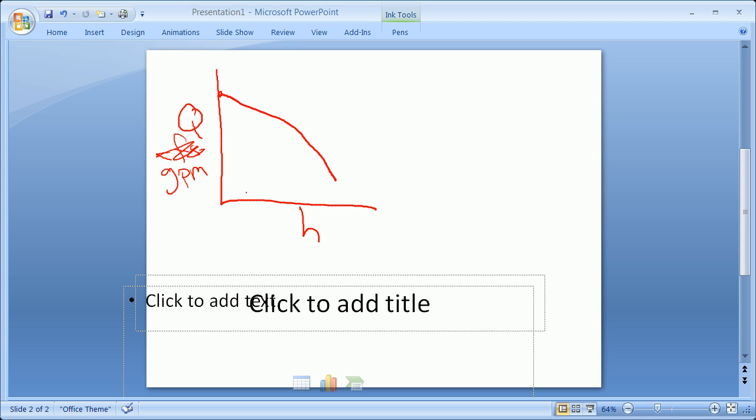If you start with the head being low, in other words just the static head, they start pumping a bunch of water, but because they're pumping a bunch of water, there's more head loss, therefore they pump less water, and they find this point where they operate, an operating point. A fair bit of engineering goes into the nuance of that. There is one other curve shown on a pump curve, and that is efficiency. What you'd like to do is get that pump working at a point where it's most efficient and giving you the water you want.